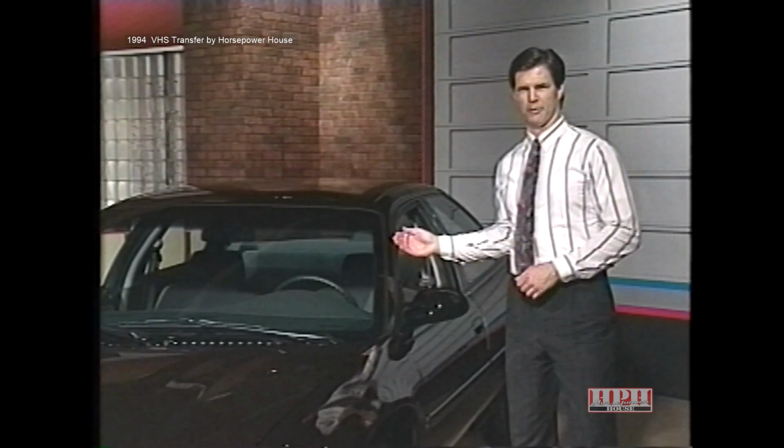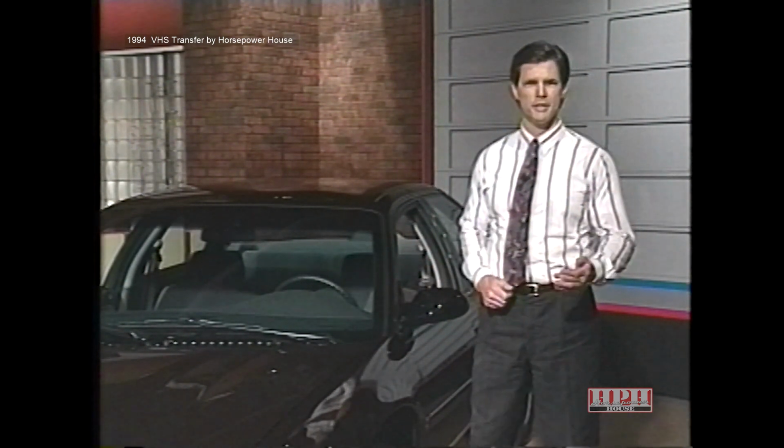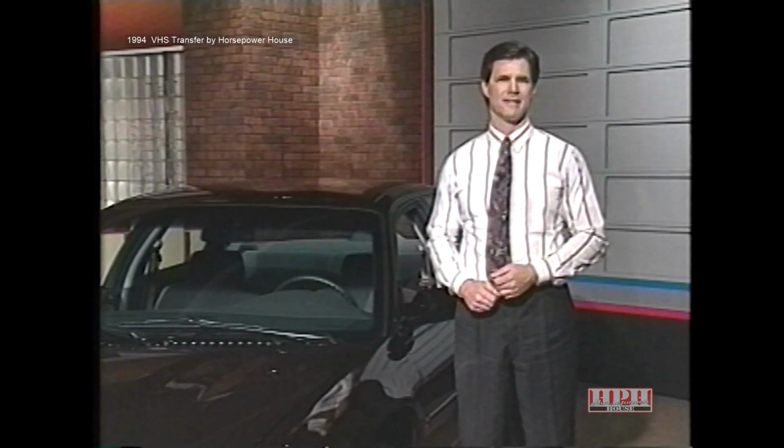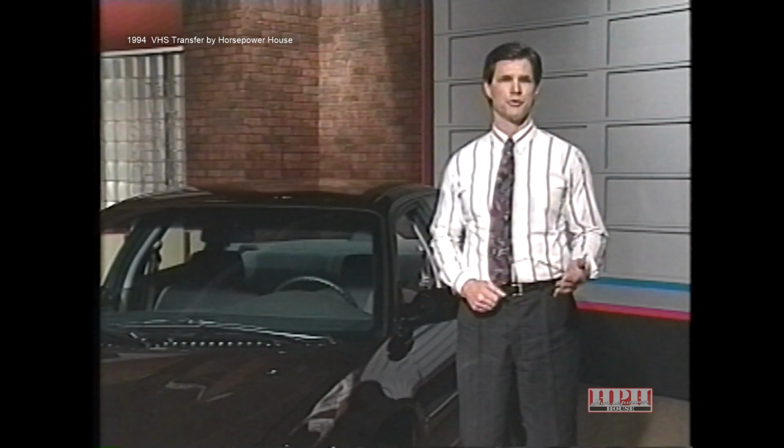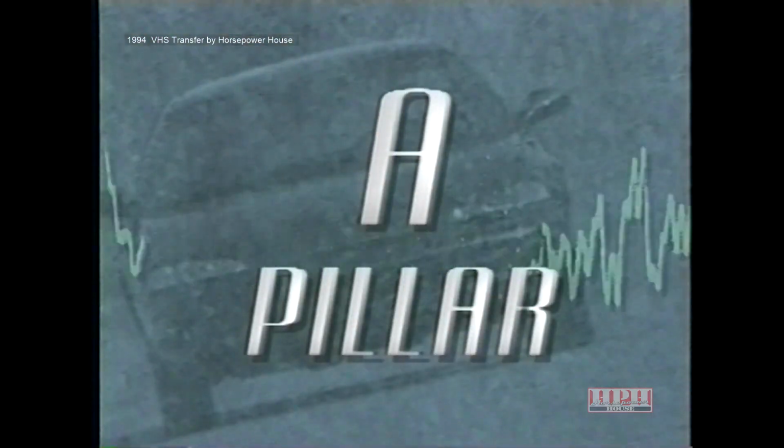We'll start at the A pillar and work our way back to the C pillar. In each instance, we'll first cover wind noise leaks, such as a roar or hiss at a constant volume, and then cover traffic noise leaks, which are more noticeable when another vehicle passes by.